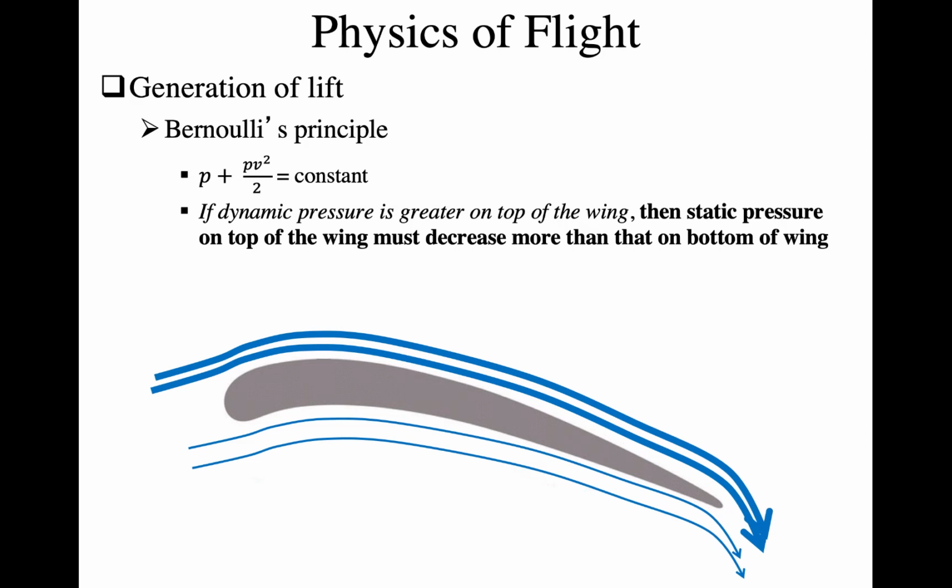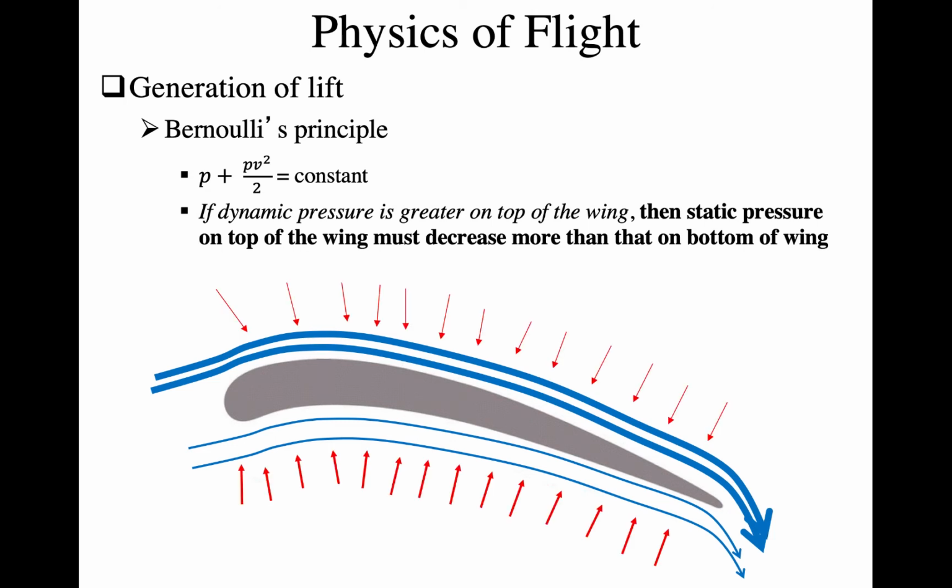So just by having any kind of dynamic pressure, you're going to see a decrease in the static pressure. But the more you have an increase in dynamic pressure, the smaller the resultant static pressure is going to be. So since we've got these big blue lines here on top indicating higher dynamic pressure compared to the smaller blue lines and the smaller dynamic pressure on the ventral surface, we're still reducing static pressure, right? Remember how big those red arrows were when there was just no dynamic pressure? You are reducing static pressure, right?